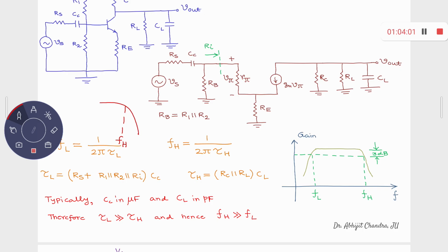So that C should be in the range of pico. You have already observed that for internal capacitors it was in the range of picofarad, 11 picofarad, 1.5 picofarad. So there also I take CL in picofarad. Then picofarad multiplied with kilo ohms gives a product in nanosecond. Now if it is in nanosecond, that means hundreds of megahertz. That means it will not interfere.